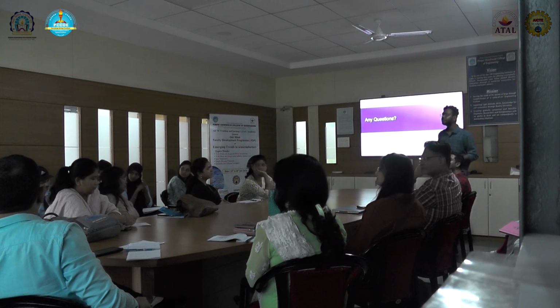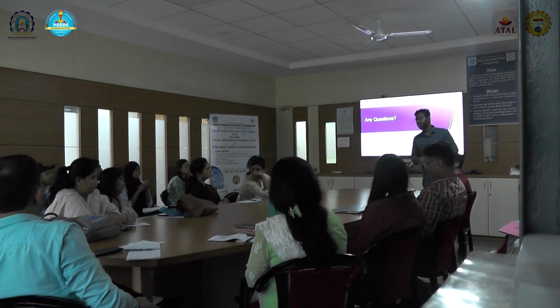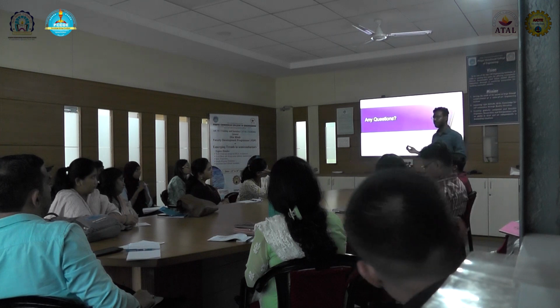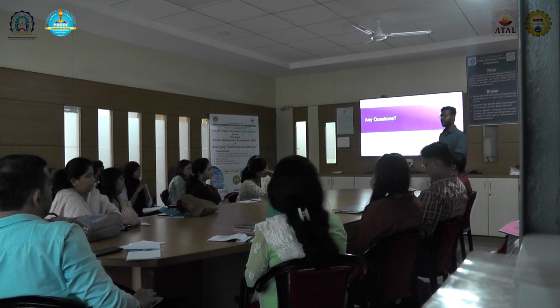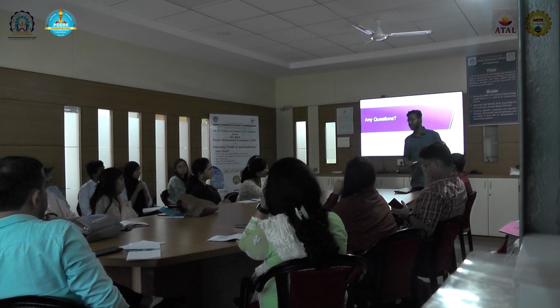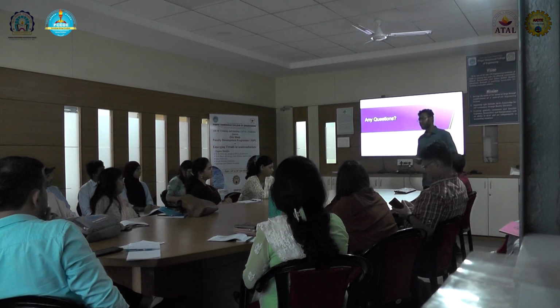How do we know that we have covered all the scenarios and assumptions? Yes, there we have something called cone of influence, like coverage in simulation. We also have something similar in formal. We have a sign-off process where we check whether we covered all the legal behaviors or not. That's the final step to make sure that the design is legally exercised.